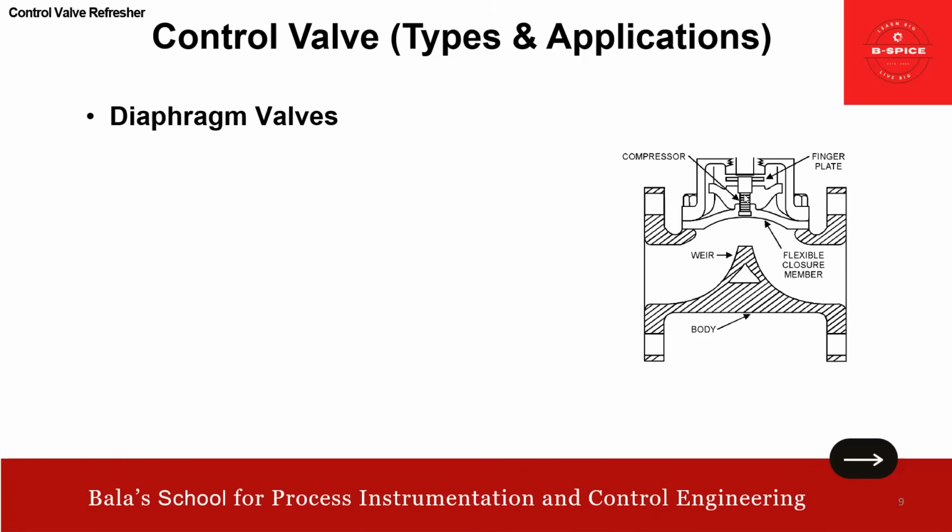So the valve actuator is in contact with the inner membrane of the valve when it is in the open position. Okay, friends. So when the user desires the valve to be shut, the actuator is pressed and this membrane is pushed into the edge of the solid dam here, thereby closing the valve.